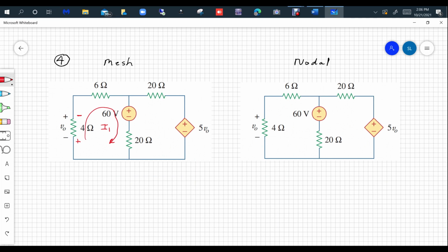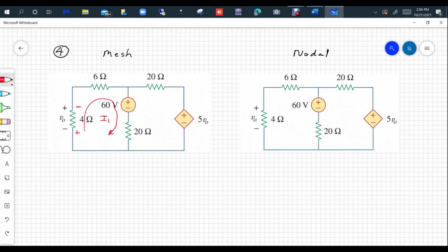But what I would do is call that a clockwise direction, so you can use the techniques we used in the past. I2. You put your plus, we had to go in that direction. We had to put a plus to minus there and had to put a plus to minus there. I didn't finish that first loop. In the second loop, on this side, I put a plus to minus because I2 goes in the opposite direction. I put a plus to minus there. That is very important that you put those in.